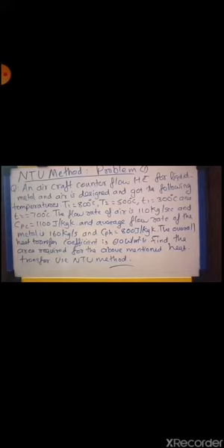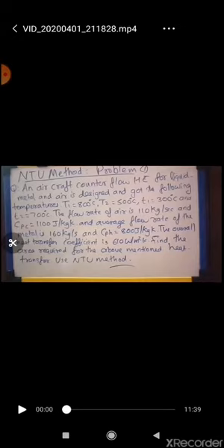Overall heat transfer coefficient is given as 610 watt per meter square Kelvin. Find the area required for the above mentioned heat transfer. Okay, use NTU method. This is the question.